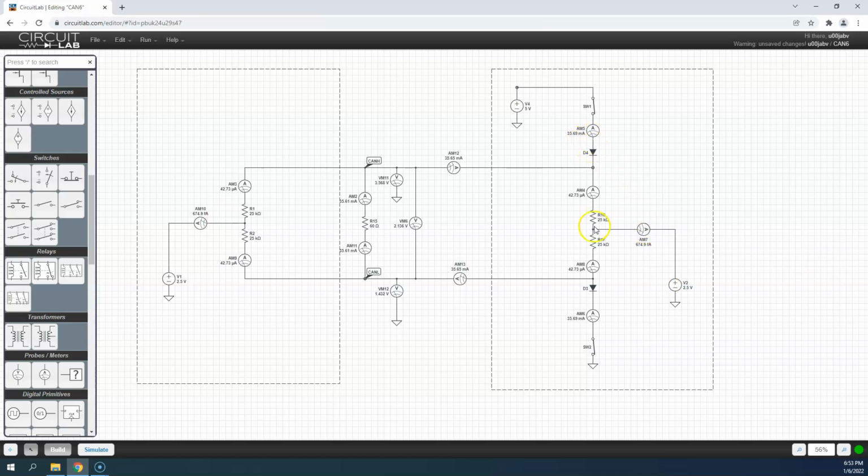So this is zero. I really have 0 amps going from here to here, so no current is virtually flowing. Probably messed that all up for you, but sorry. The point I wanted to make is that when you're driving something, I can still have this held at 2.5 volts, which may be confusing. Why can this point still be 2.5 volts? It's because I can't access this. This is still allowed to be at the recessive state.